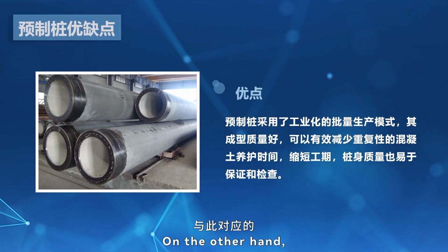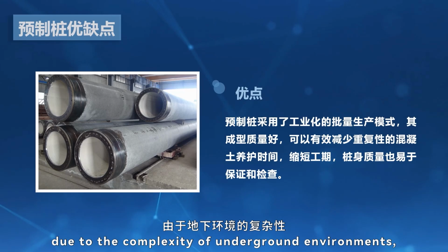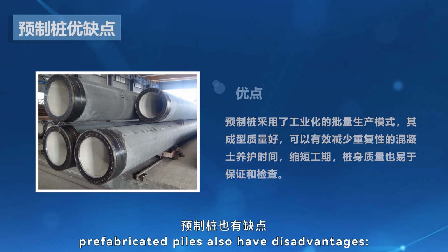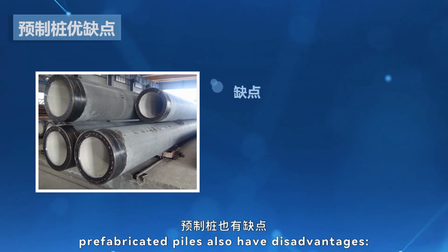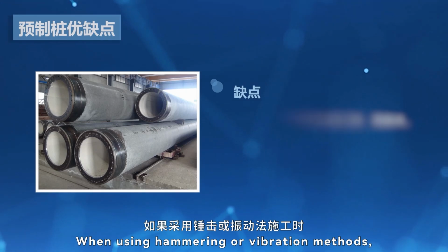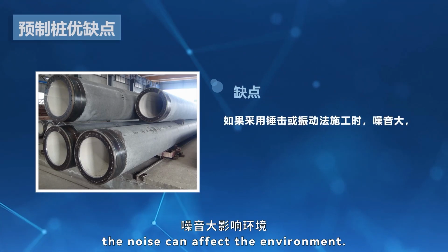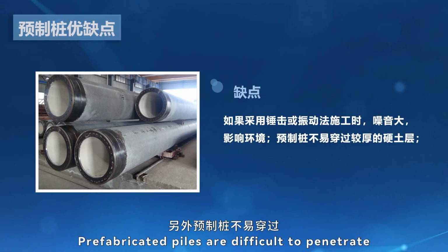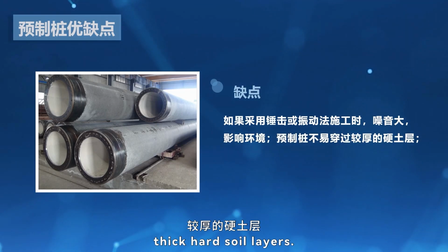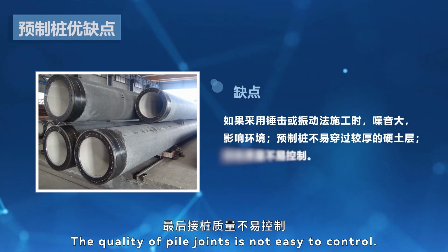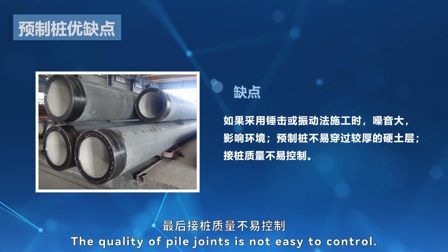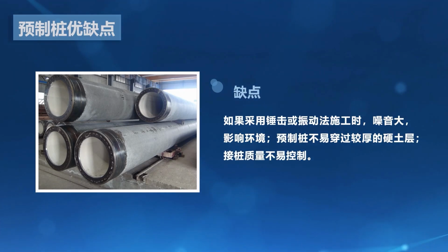On the other hand, due to the complexity of underground environments, prefabricated piles also have disadvantages. When using hammering or vibration methods, the noise can affect the environment. Prefabricated piles are difficult to penetrate thick, hard soil layers. The quality of pile joints is not easy to control.